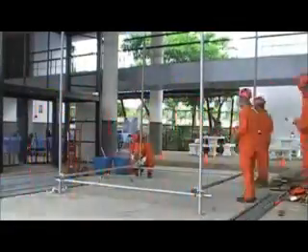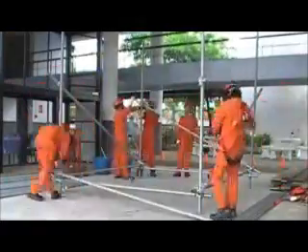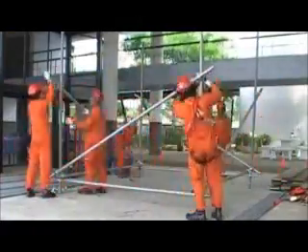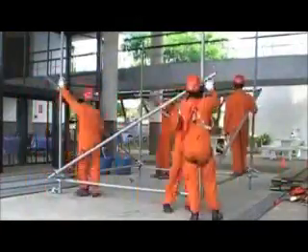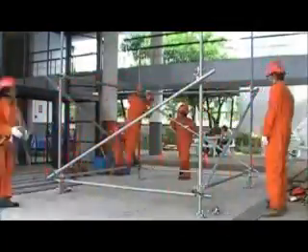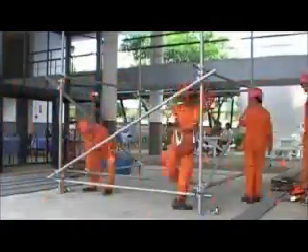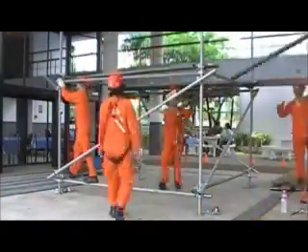Put standard or post and engage by bearer and runner. Lateral span can be 6 feet and longitudinal span can be 6.5 to 10 feet depending on load capacity of the platform. Tube diameter for scaffold is generally 63.5 mm and thickness 4 mm. Use standard couplers and ledgers for joining.